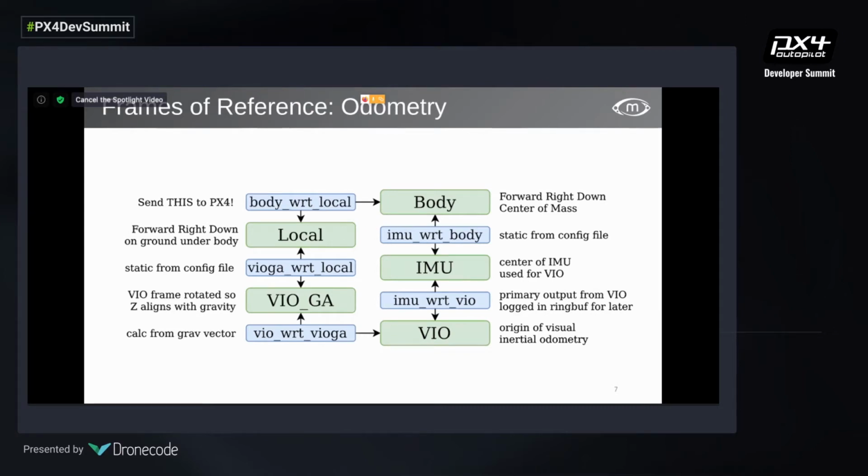Translation is a simple 1x3 vector, x, y, z, whereas the rotation can be represented as either a quaternion, a roll pitch yaw, or a rotation matrix. For simplicity of the math, I highly recommend just using rotation matrices. However, TF2, if you elect to go that route, will handle all of that in the background for you.